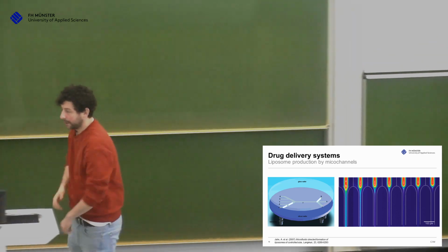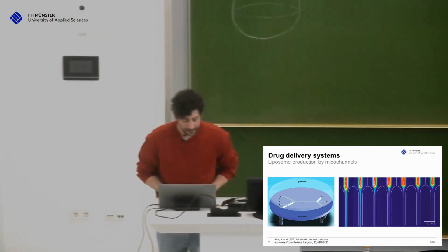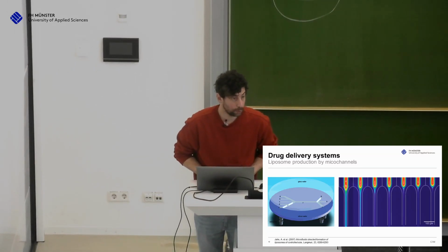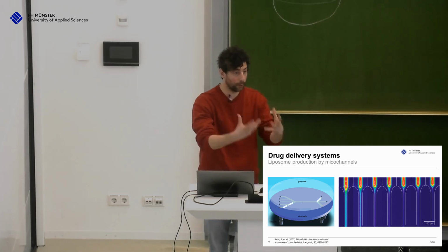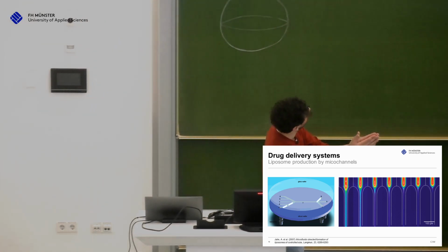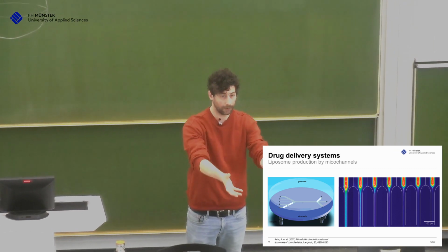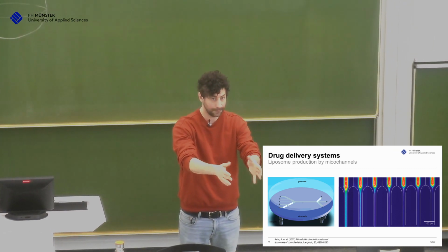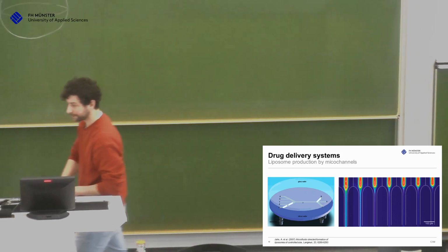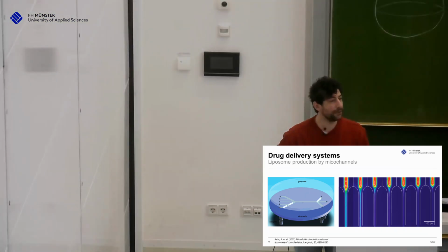But it's important for you that next to these colorful parts, left and right, there is still a stream, okay? And what is changing is the ratio of the two streams. So here is a lot of IPA, isopropanol, and the amount is decreasing. But the volume flow rate is the same for all 2, 4, 6, 7 experiments, okay? So the amount of overall liquid going through the channel is the same, but the ratios are different. And this is something very easy to adjust, okay?